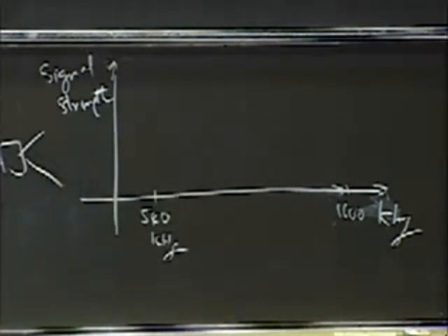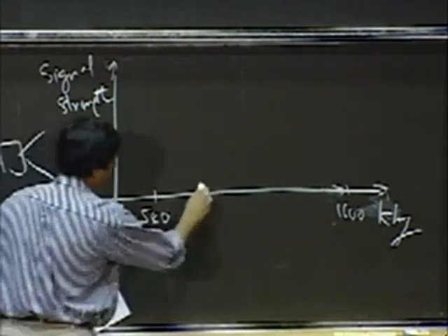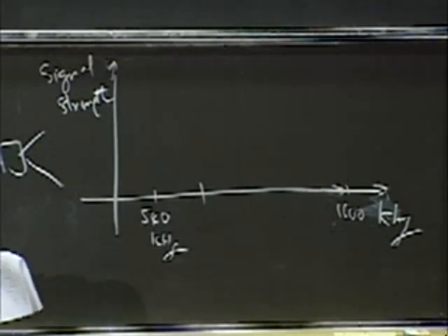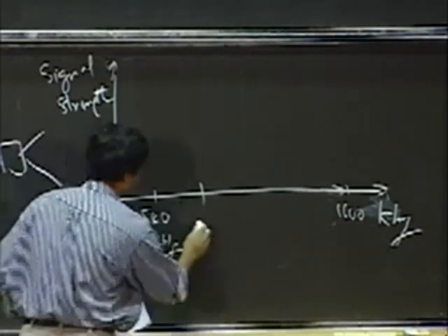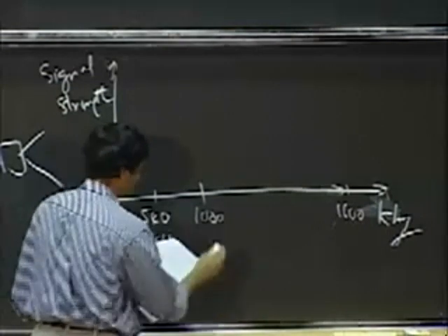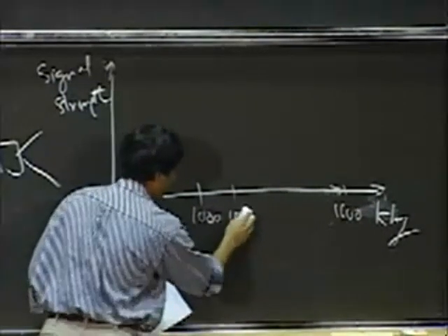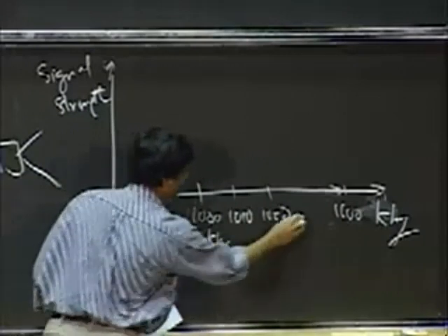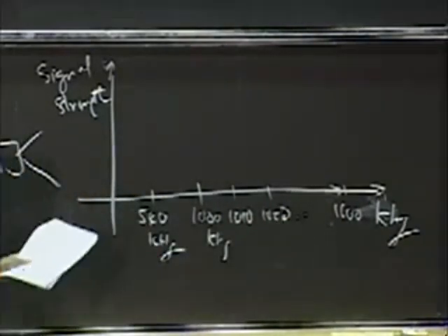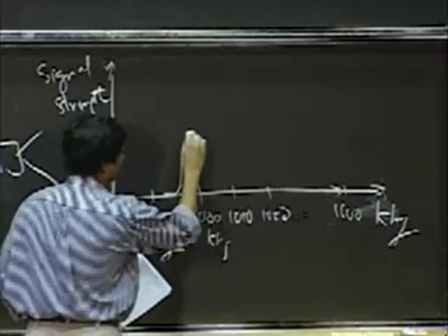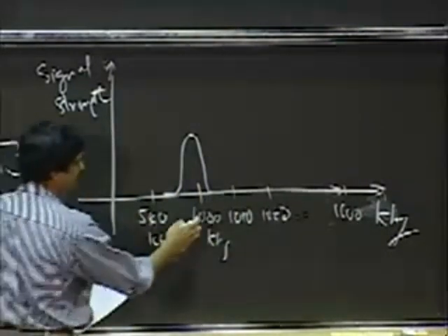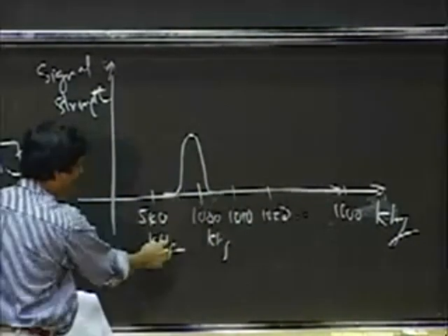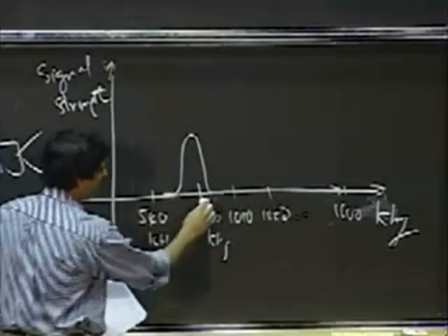So if you look at your radio tuner, you'll see 540 kilohertz all the way up to 1600, and you can tune your AM radio. And the way it works is that each station is given 10 kilohertz of spectrum here. And so this is at 1,000 kilohertz, 1,010 kilohertz, and so on. And each station transmits its signal in plus or minus 5 kilohertz around that point.